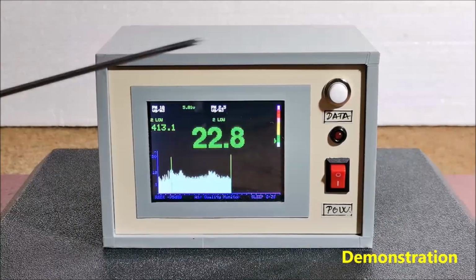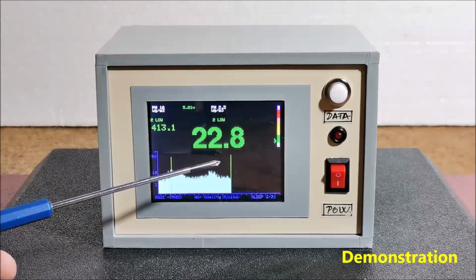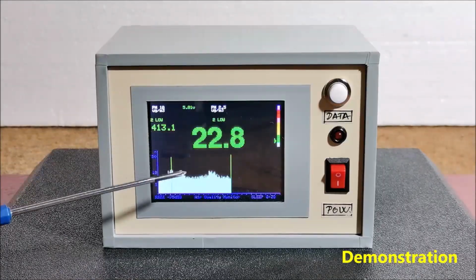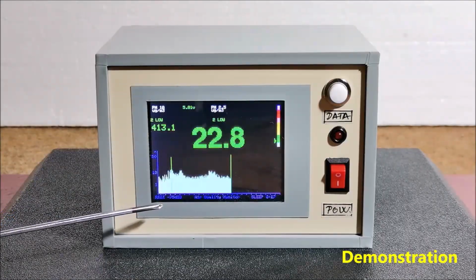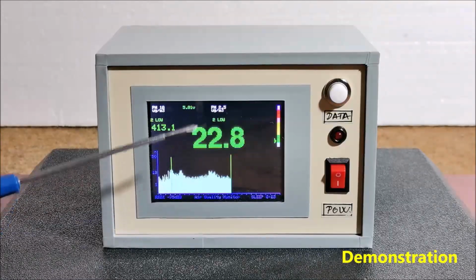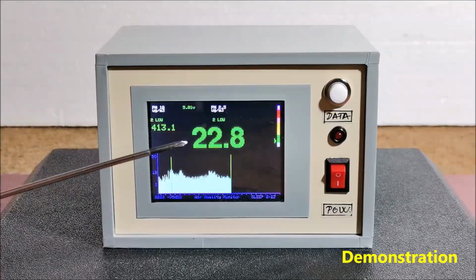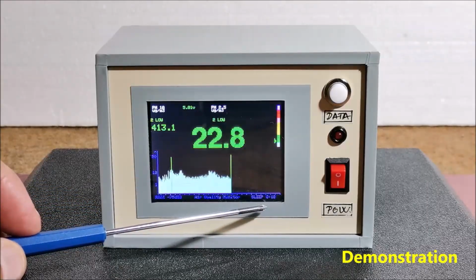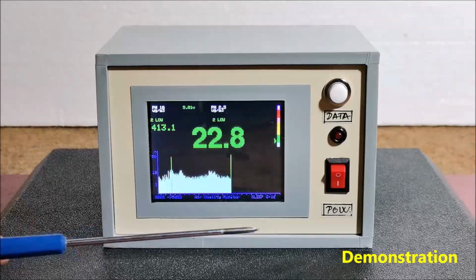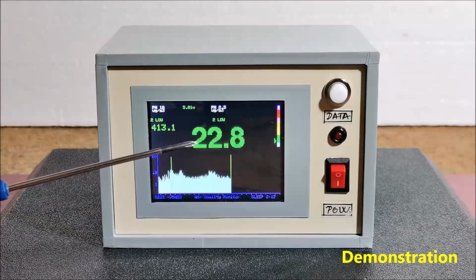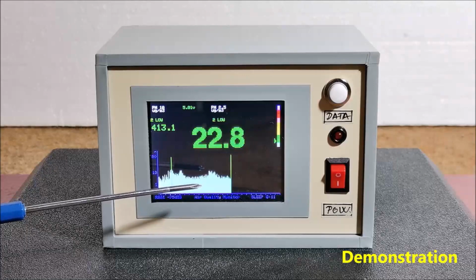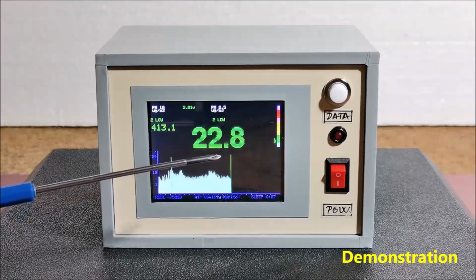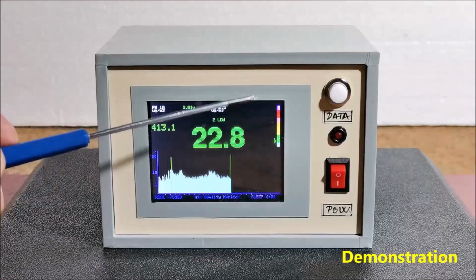The screen shows the concentration of the PM2.5 and PM10 particles, as well as the strength of the Wi-Fi signal and the value of the supply voltage. Also at the right corner we can read the sleep time of the sensor. As we see, the color of the graph changes from light green through yellow-red shades to magenta, depending on the air pollution according to the UK DEFRA scale.